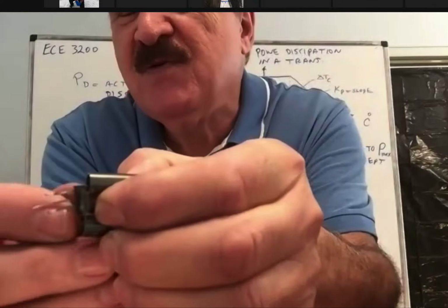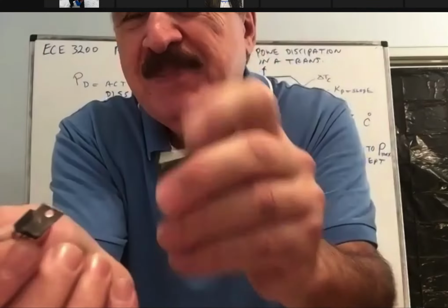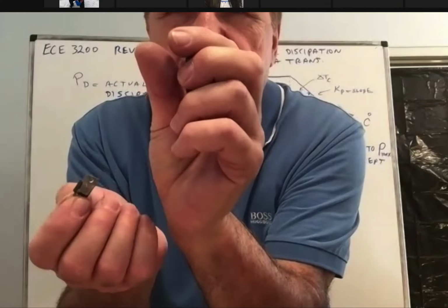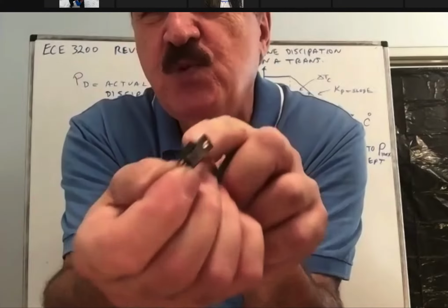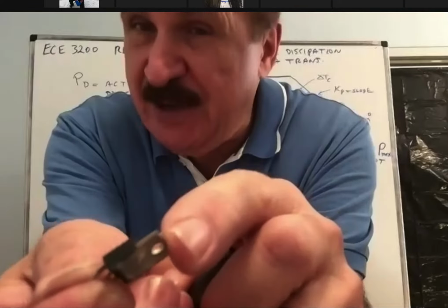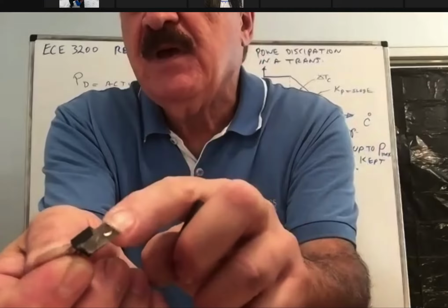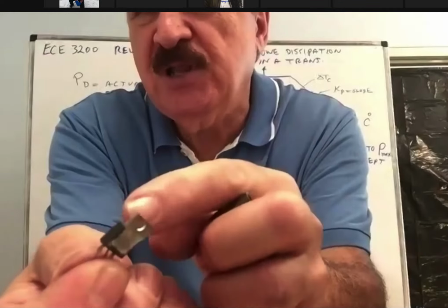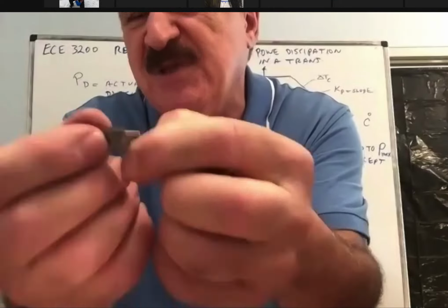The junction, when it contacts the case internally, that we don't see, it's inside, it does have a little bit of thermal resistance. In other words, the junction temperature inside the device will be a little higher than the case temperature. So we have to be aware of that fact. Usually, you can't do anything about that internal heat transfer resistance because it's built into the device.